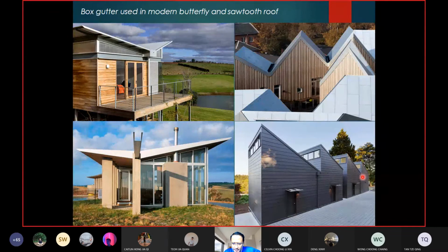So he also got a rain head, right? And I believe for this part here at the back, there might be another component, because we cannot see an eaves gutter there. Okay, most likely the designer intended to just let the water flow from the roof, okay, to the ground. So maybe there's underground drainage located here in between the two blocks. Okay, but what I wanted to show here is basically the rain head and the downpipe.